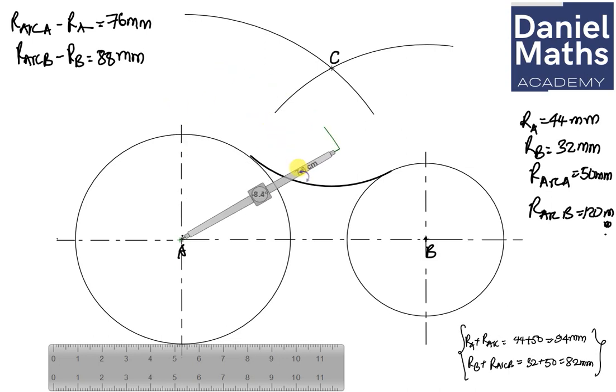Let me start again from this point, please take note of that. Let me start somewhere here. So I'm making this arc from this point. I'm making this arc from here. So I have this to this point, and then let me turn this back and measure the second point, which is 88. So come back to this point and then measure 88. So 88 gives us this exact point. Let's be careful to take our measurement properly so that we don't have an issue with our arcs joining properly. So 88 is somewhere here.